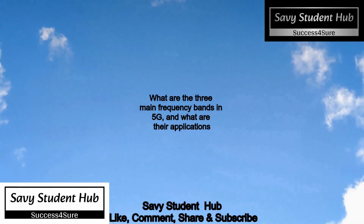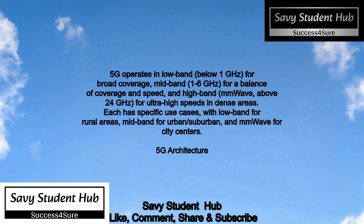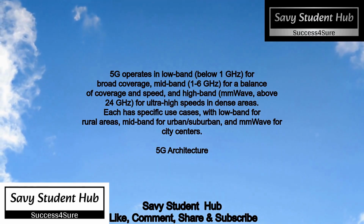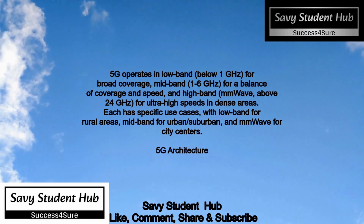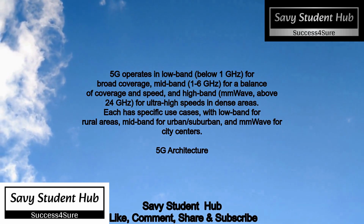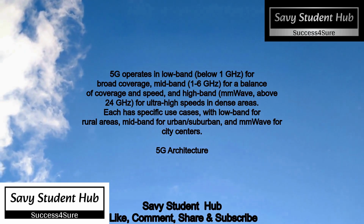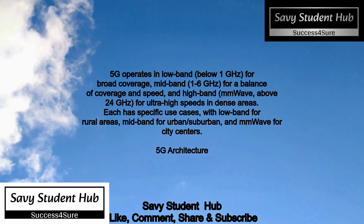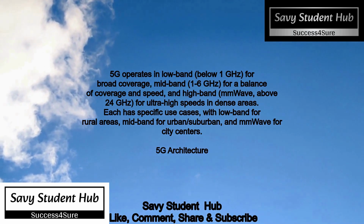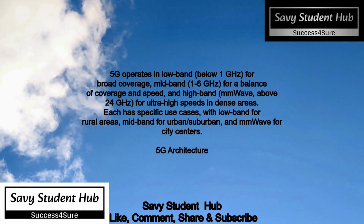5G operates in low band, below 1 GHz, for broad coverage, mid-band, 1 to 6 GHz, for a balance of coverage and speed, and high-band, mmWave, above 24 GHz, for ultra-high speeds in dense areas. Each has specific use cases, with low band for rural areas, mid-band for urban and suburban, and mmWave for city centers.